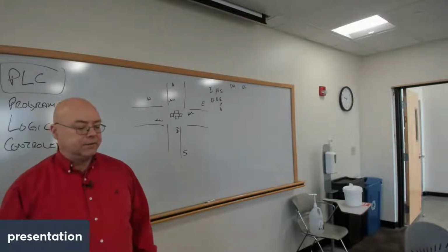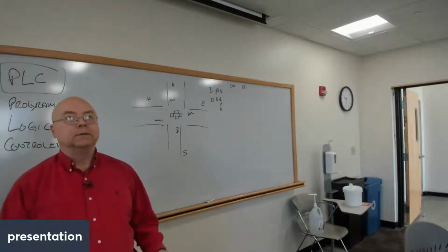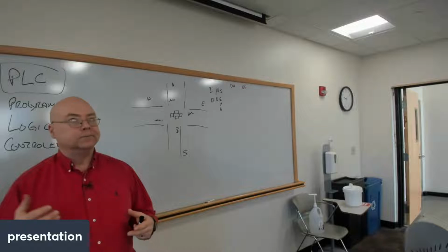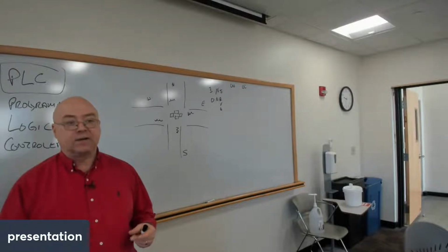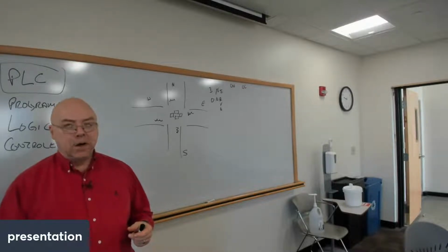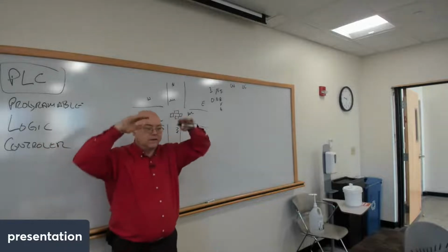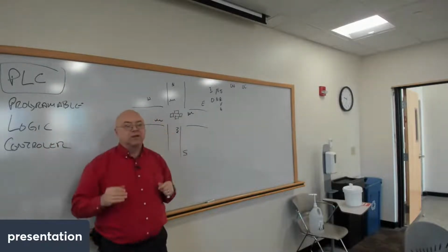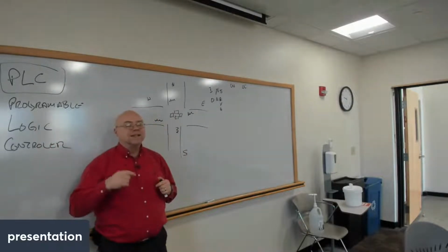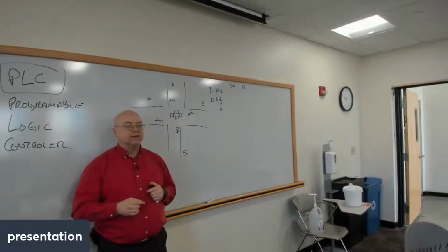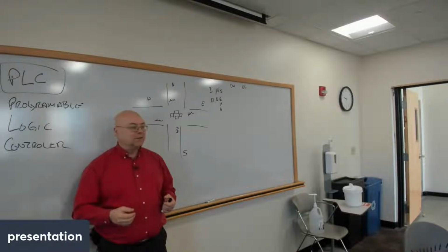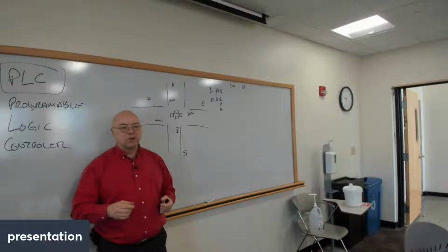If you end up doing PLC programming or PLC maintenance in a factory, most of the time you're not debugging the program. When you create a new program, you've got to figure out, does it work? Did I screw up making the program, right? Is my logic correct? Once it has successfully operated and it screws up, it's always because one of the sensors is broken. And then you have to figure out which sensor is broken and what's broken about it.